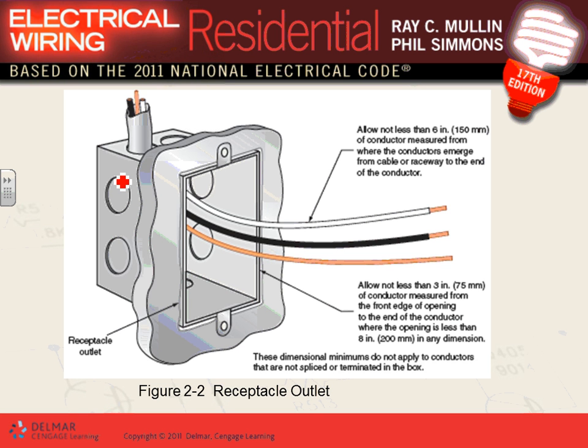I'm sure, Karen, you guys have seen that one when you were with Karen. This will tell you that when you are wiring with cables, the length of the wire as it enters from here all the way up cannot be less than 6 inches. Anybody know why? 6 inches, and from the point it leaves the box right in here all the way, that one cannot be less than 3 inches.